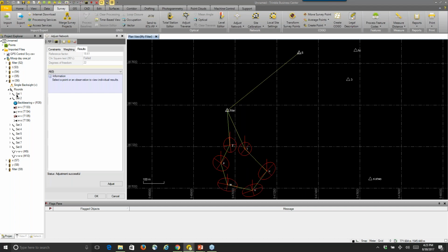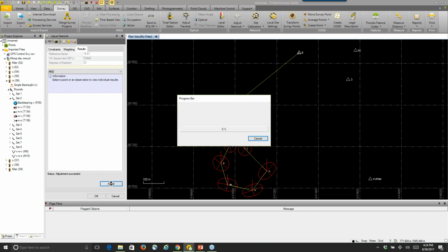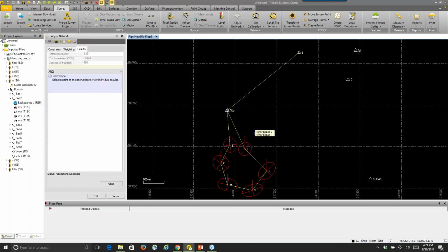Now before I do that, when we set this up, we set up tripods, prisms, and instrument, and we did 8 rounds back to back. We didn't go back and check filter. We didn't go back and check U. We didn't check anything. We just did 8 sets of rounds, which means if there was an error in any of our tripod setups, this set of rounds would not detect that. So we really have a precise mean angle set of rounds, but all the individual observations have correlated, or could have correlated, errors. And because of that, we only use the mean angle information.